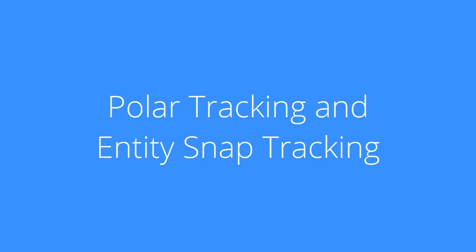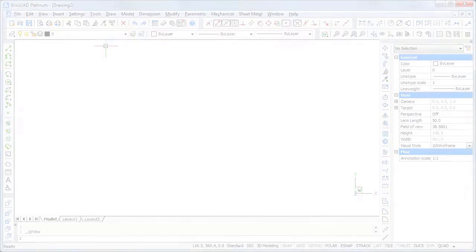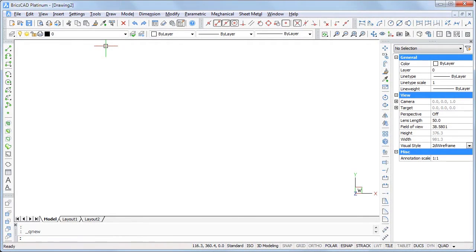Welcome to BricsCAD TV. This tutorial is about polar tracking and entity snap tracking. Polar tracking assists you to draw at exact angles, at fixed intervals and optionally at specific additional angles.